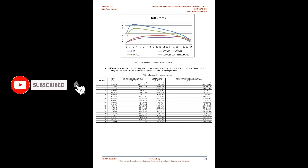4. Conclusion. From all the above analysis, it is observed that for a high-rise building of 20 stories, building with composite column is more efficient. It is observed that displacement and drift are reduced substantially and stiffness of the building increases in presence of shear walls. Hence it is concluded that composite column building with shear wall counters seismic force more as compared to other models. In case of RCC framed structure the lateral displacement is very high.